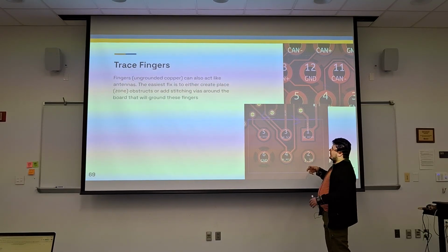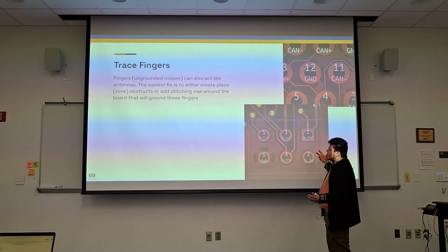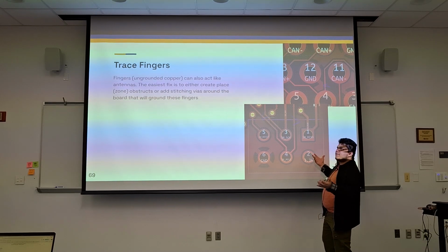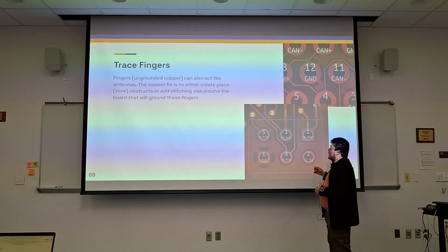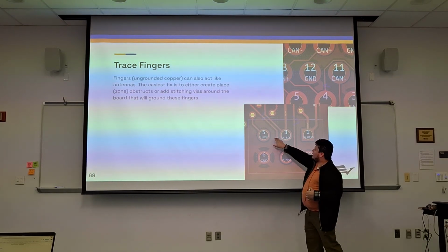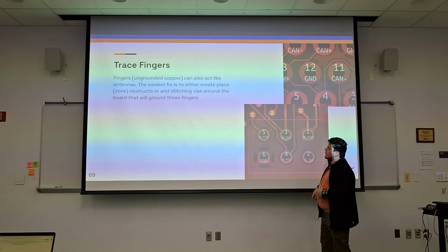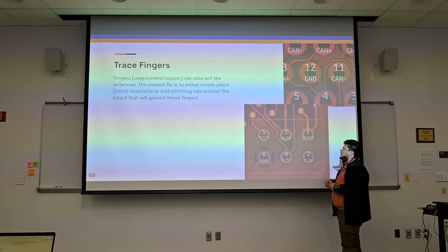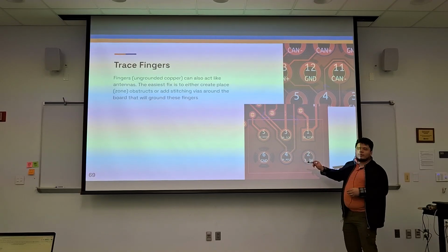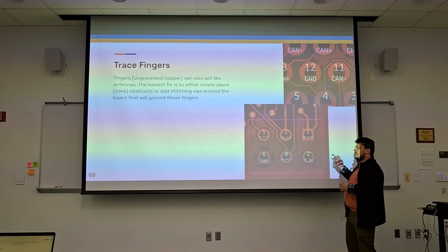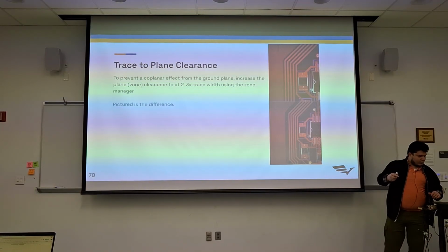But if you have a requirement where you need at least, say, 20 mils of copper, then this is not 20 mils, you're not going to get copper over there, and that's not an issue anymore, right? Those are different ways of looking at that. It's not the end of the world, but best practice is to remove these where possible.